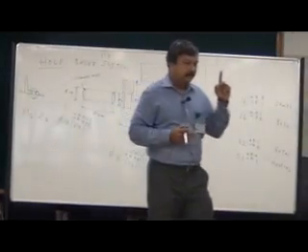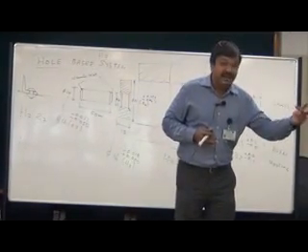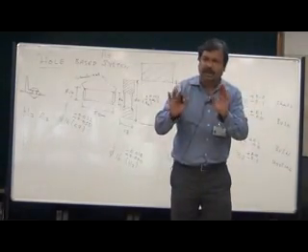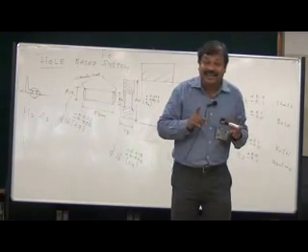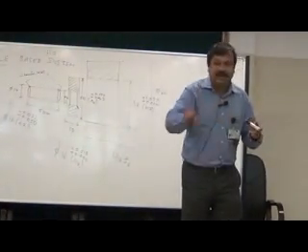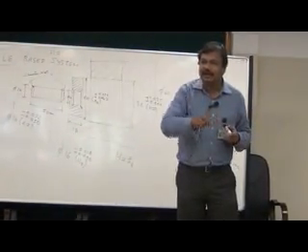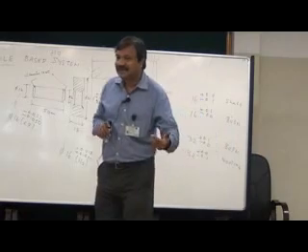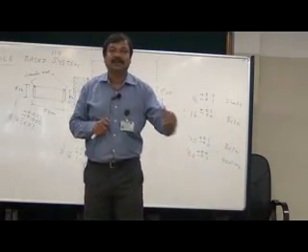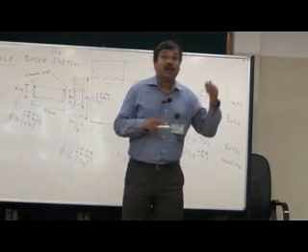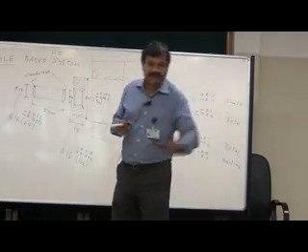Taguchi begged to differ. He wanted to resort to a different approach. What is the different approach? Of course, solving the root cause of the problem is one way, but that is an expensive route. Can I assume that the root cause will remain? The root cause of the problem will remain. But still, make my design more robust so that it is insensitive to these process variations. If you could design a system like this, that is called a robust design.